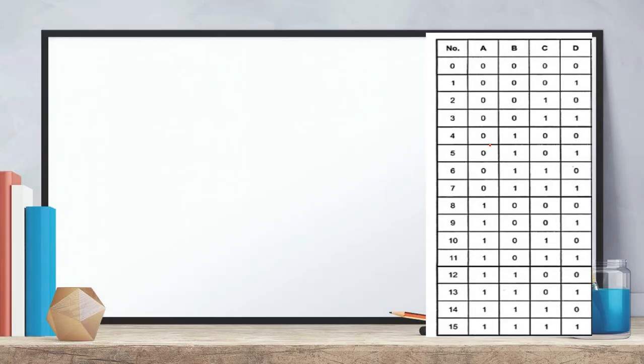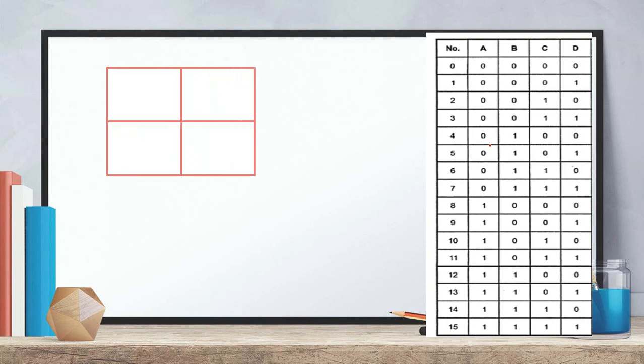Now we can move on to the KMAP for 4 variables. So for a 4 variable KMAP, how many cells are required? Usually 2 to the power of n is the formula. Here 4 means 2 to the power of 4, which is 16 parts. So we can go with a 4 by 4 grid. We already know 0, 1 and 4, 5 from the 3 variable map, so I won't go too deep on this. For 4 variables, we can equally divide vertical and horizontal into 2 and 2. So the first MSB bits, A and B, we take as rows, and CD as columns.